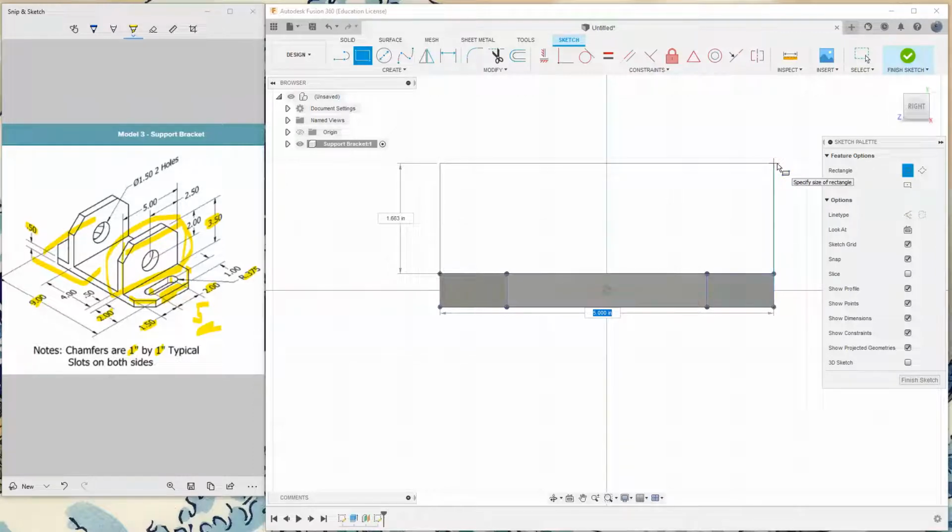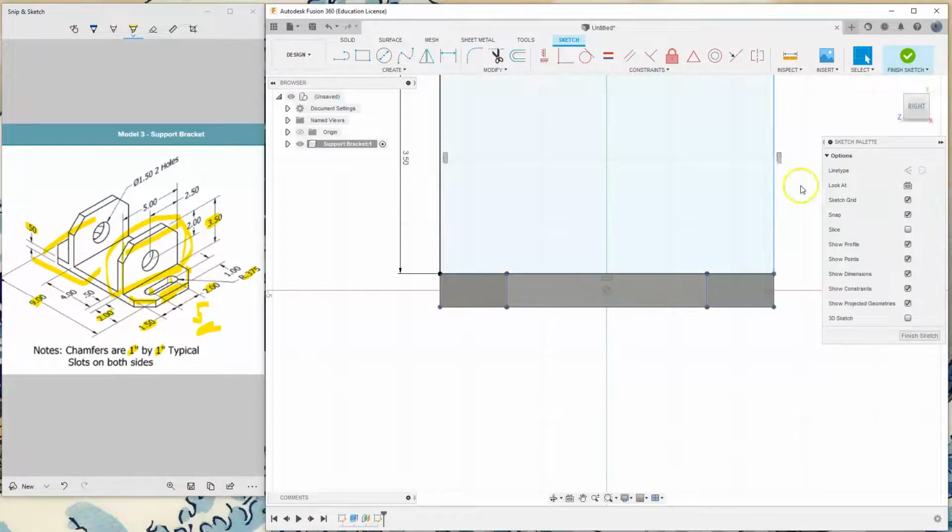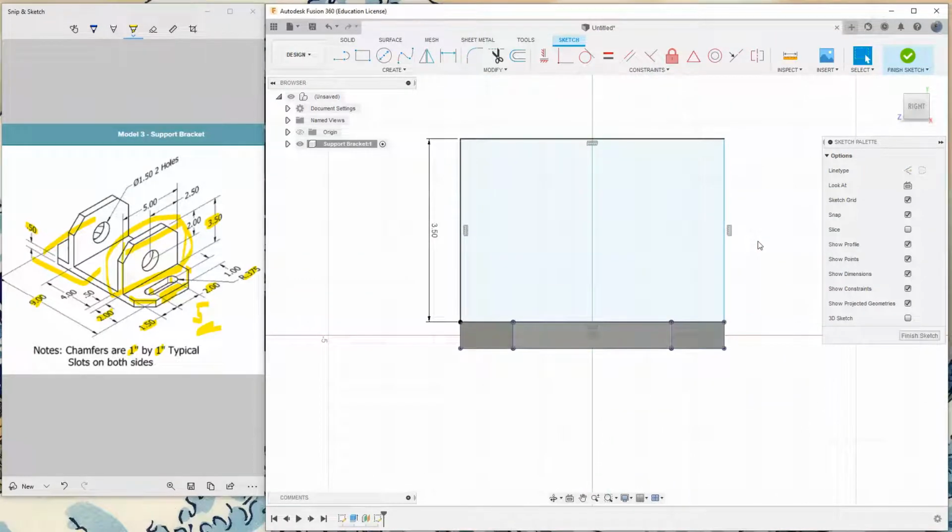And then, as you can see, it already said it's 5, so you could hit tab. And then the height will be 3.5. Okay, so now you could press enter. Let's see if that worked. Okay, looks like the measurement from below did not work. So let's try to go use the sketch dimensions, just dimension from here to here, and it's 5. All right, so now it's fully constrained.